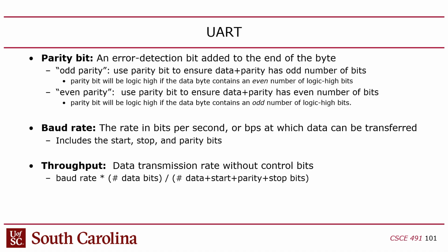So to answer your question, when you program the Arduino, you're generally programming it from a PC over USB, and you can do UART over USB, right? I don't think you can do SPI over USB. That's not a thing, right? So if you want to program your Arduino, UART is an obvious choice, because there's built-in support for UART over USB, right? Does that make sense?